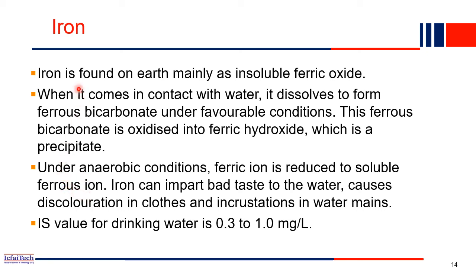The iron quantity in the water also should not be too high. For drinking purposes, iron should be 0.3 to 1 milligram per liter, and it should not be more than that. If you visit some village areas where water is collected from a bore well, like underground water collection, near the water supply you will find a reddish color mark. That is because of iron.